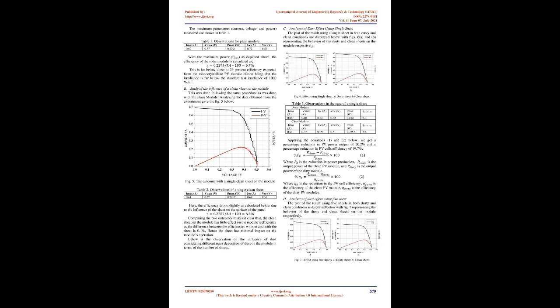A multimeter was connected as a voltmeter, with the range selector switch set to position DCV20. Another multimeter was connected as an ammeter with its range selection switch at DCA10. The lamp arm was put in the south position with the solar cells in position 90 degrees and the brightness controller fixed to its maximum, level 10, which gave an irradiance of 170 W/m².